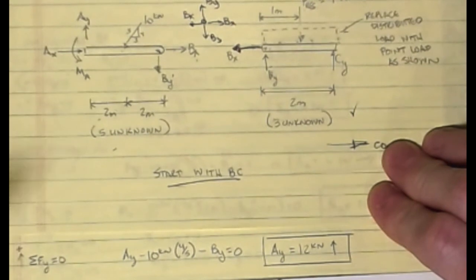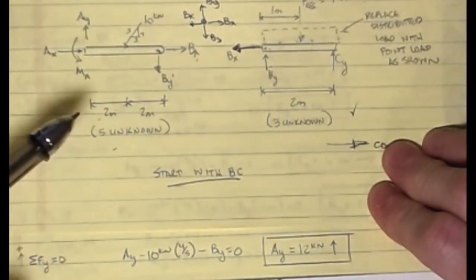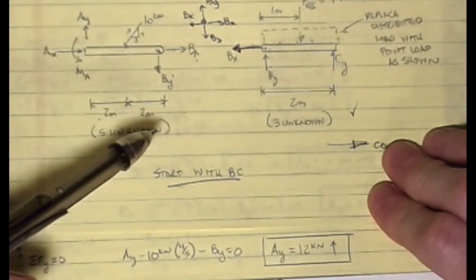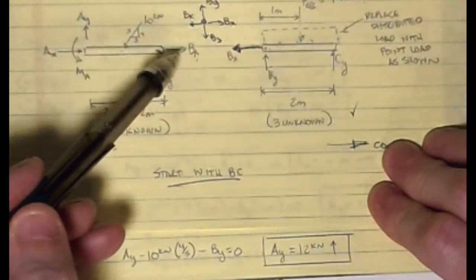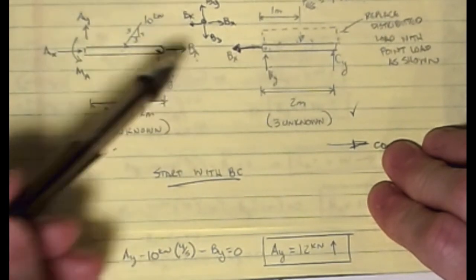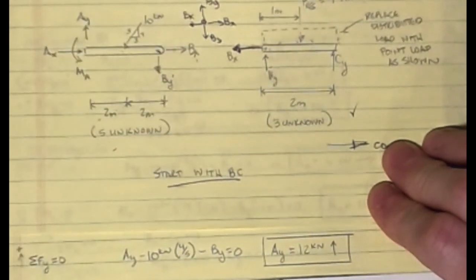All right, so again, you're looking for hinges and you're blowing it apart at the hinges, and you're playing with the pin forces and how they act on the members. So again, we had 2 members here, that's why the Bx's were opposite and the By's were opposite. If I had a 3rd member coming in, we would have to do something a little bit different, and I'll show you that a little bit later.